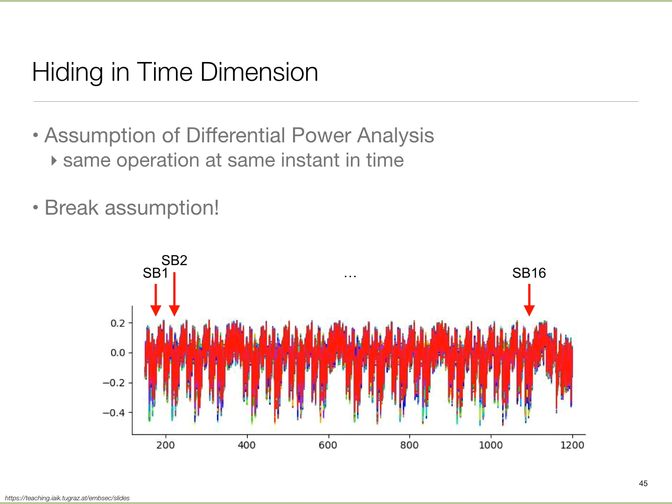Another thing you can do is to shuffle the computation. If your algorithms allow it, you create a randomization in the time dimension. A lot of these techniques depend upon the attacker knowing when the operation will happen.